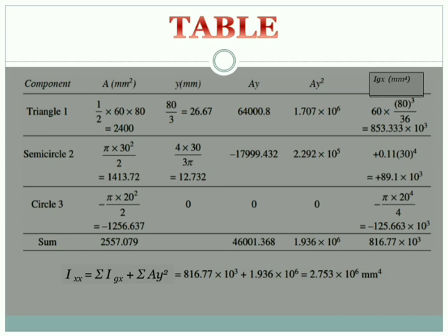Area of the semicircle is pi r square by 2. Then y, okay, y is 4 into r by 3 pi, and here minus sign has to be put. I have not put the minus sign purposely, as while writing you should have that much of awareness, because the semicircle is below the x-axis. Okay, the semicircle is on the below side of the x-axis.